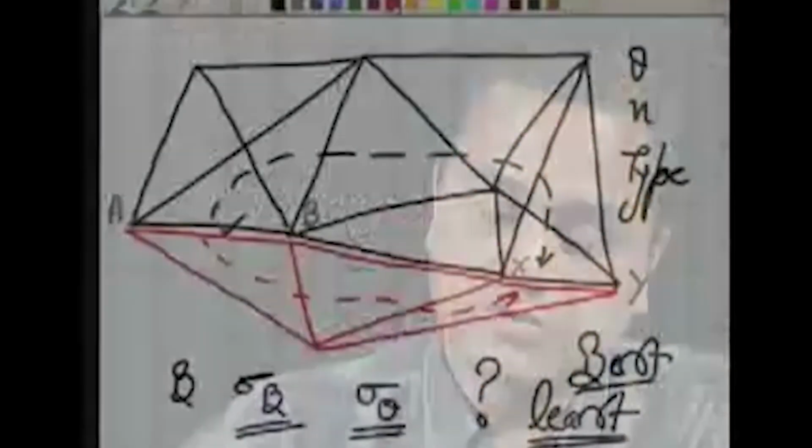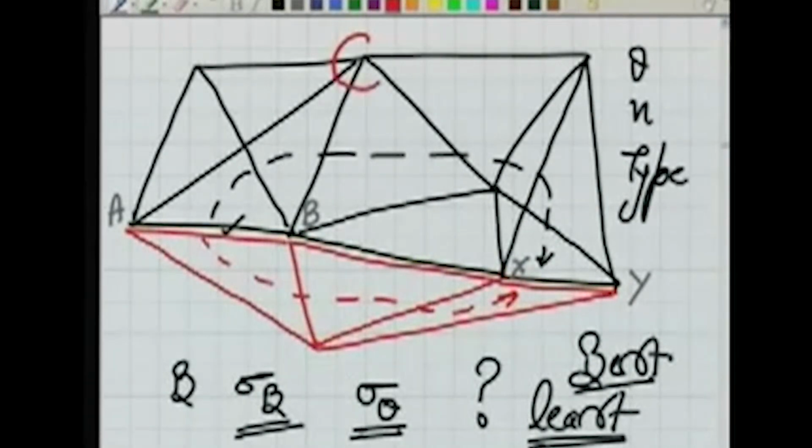Similarly, it may be possible in some situations, for example, that it was not possible to occupy this point. If this point was not possible to be occupied, by occupying these points, we can still derive these angles. So the angles which are here are derived angles, not actually observed angles. We should give less weight to those angles which are derived, while we should give more weight to those angles which are actually observed.